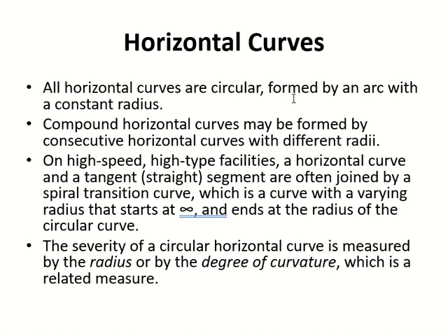Okay, now we will talk about horizontal curves, their design. In the design of horizontal curves, the shape is very important. The shape is circular. All horizontal curves have circular shape. Now you can play around with the same shape and vary it to have other types of horizontal curves. For example, we have one which is called a compound curve. In compound, it's a circular curve, but more than one circular curve is joined together. So the shape is still circular.